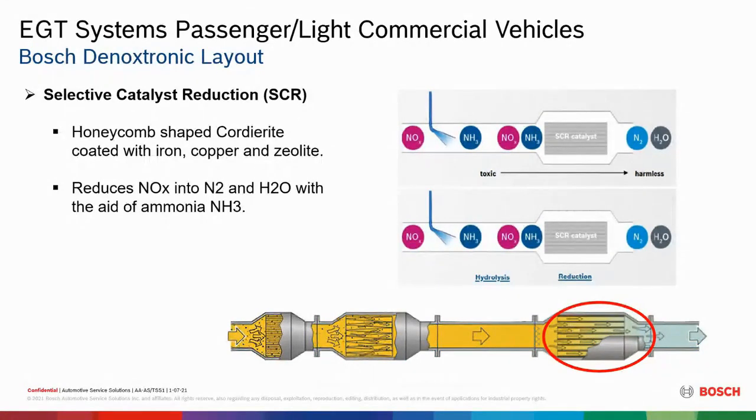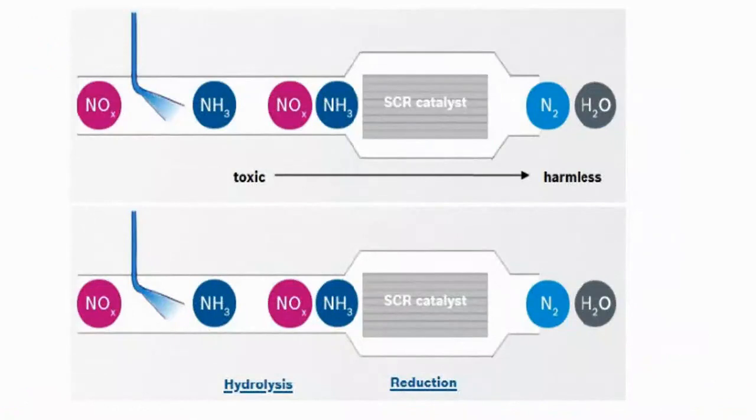And what we're going to do is, let me expand this a little bit here so you can see this a little bit better. So through the process of the catalyst here, we're going to take the NOx in, and actually we want to split that up. We can take that NOx and split it up in the DOC, believe it or not. We're going to bring that down there. So this isn't really a true reflection of what it is, but to make it a little bit more simplistic, we're going to take that NOx and the NH3 or ammonia in that. And along with the H2O, which isn't shown here, we're going to use that because there's a mixture of NH3 or urea in the DEF fluid along with water as well.